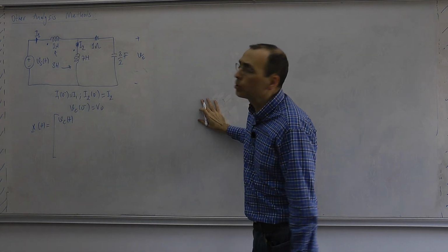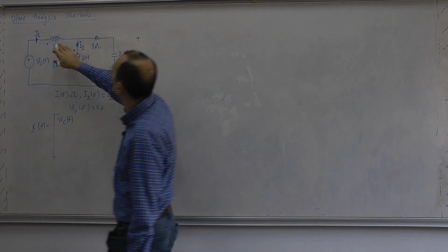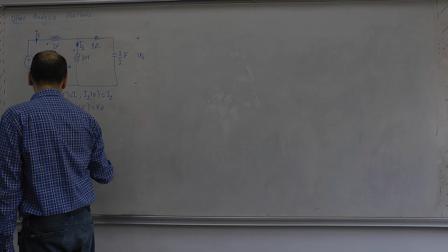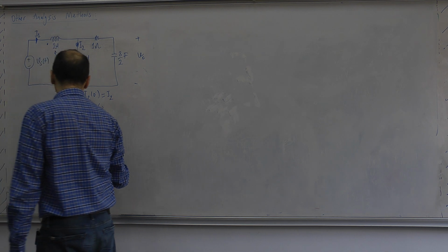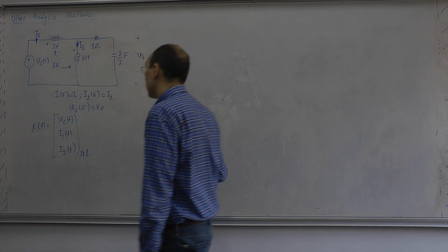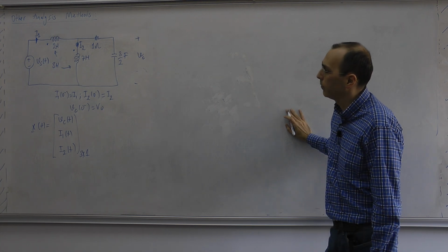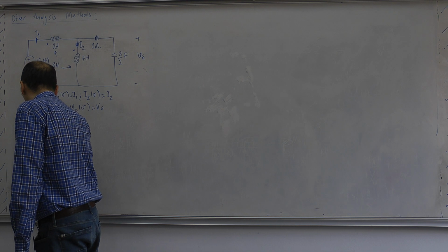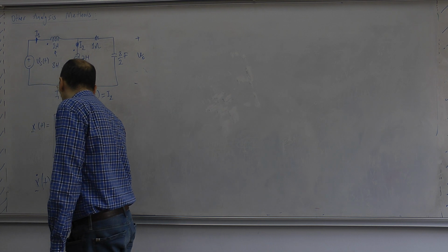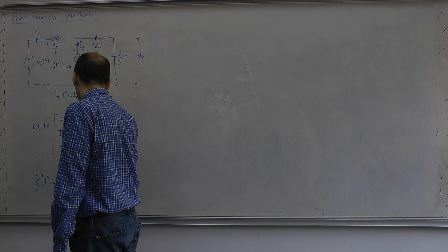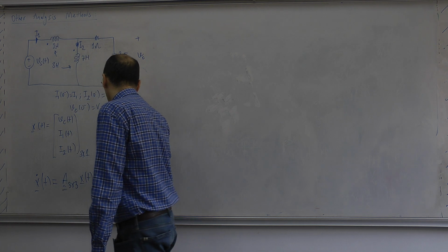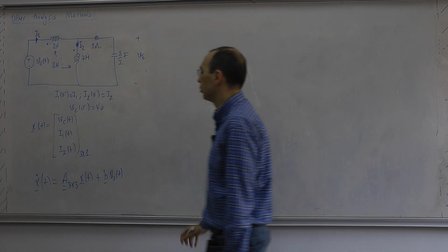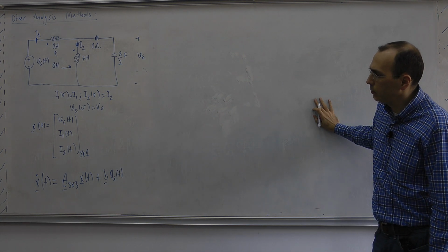And currents of the inductors on the co-tree, which are I1, I2. So this tells us that my state vector for the state formulation is a 3×1 vector. Okay. So if I write the state equation system, let's review. Then I have this 3×3 A matrix, and I have a single source, which is what we call input also. I have a state equation like that.